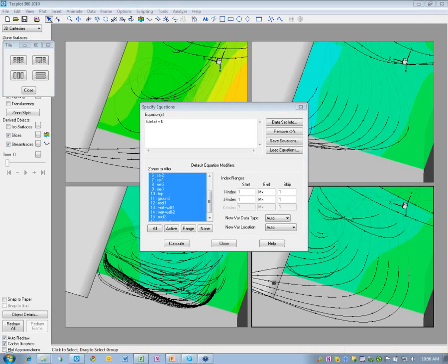There was a question about what's new in Tecplot in terms of data size limitations. Sure. In terms of hard limits, you can have up to 2 billion data points per zone. Now, practically speaking, that would require a large computer with a lot of memory. It would also be 2 billion elements as well. I'm not aware of any other hard limitations at this point.